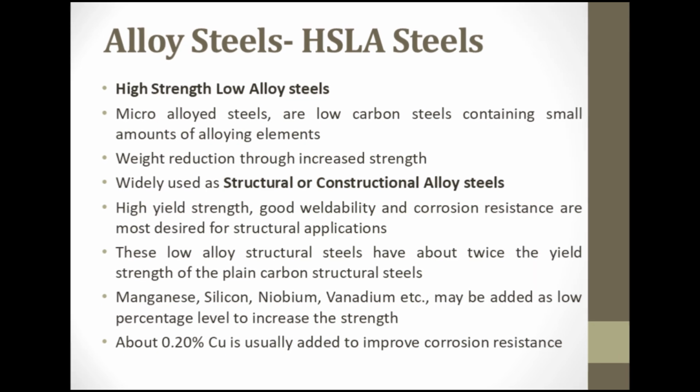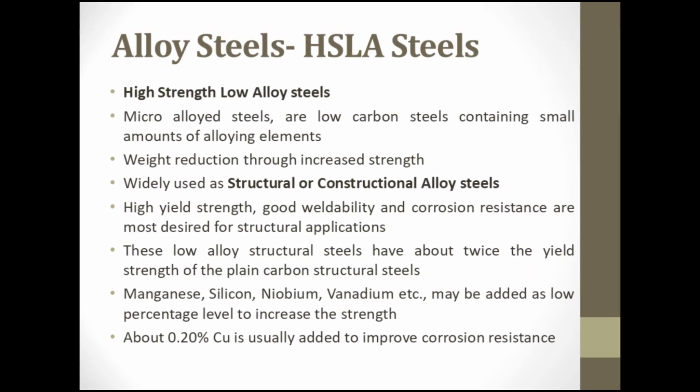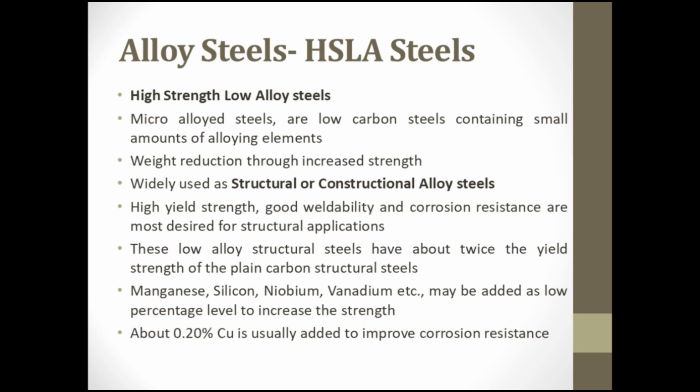Alloy steels, HSLA steels, high strength low alloy steels. Micro alloyed steels are low carbon steels containing small amounts of alloying elements. Weight reduction through increased strength. Widely used as structural or constructional alloy steels.